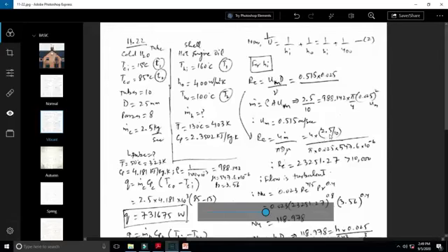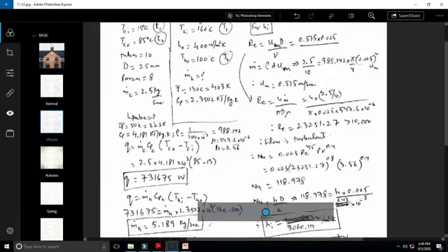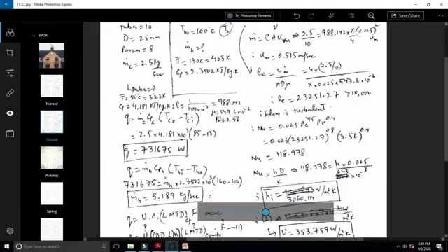So we need to divide this 2.5 by 10, because we are calculating the Reynolds number through one tube, which would be the same through all the tubes, over pi d mu, and mu would be the viscosity of water. So mu needs to be calculated in the same way the Cp of water was calculated, at 323 Kelvin.